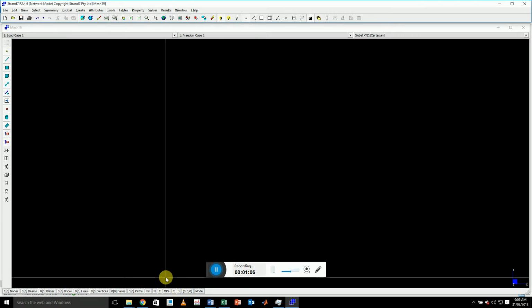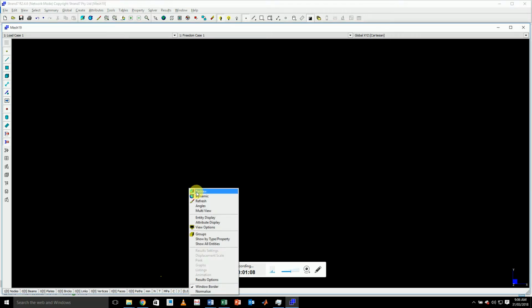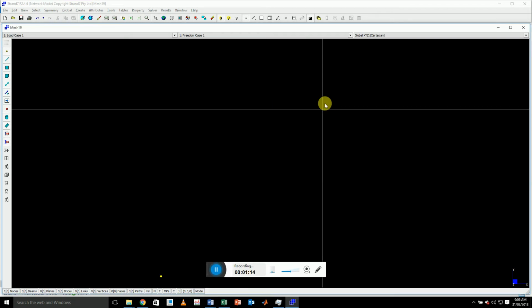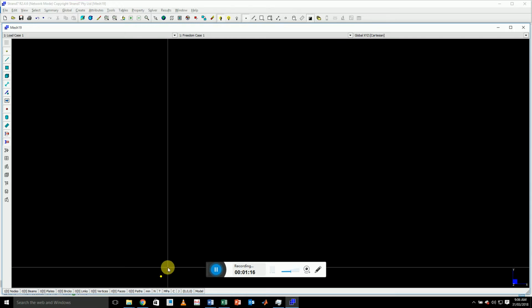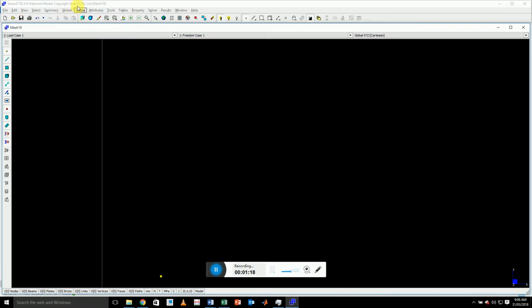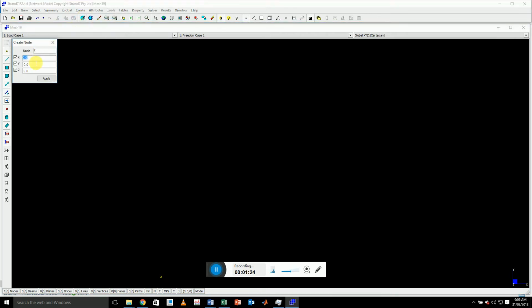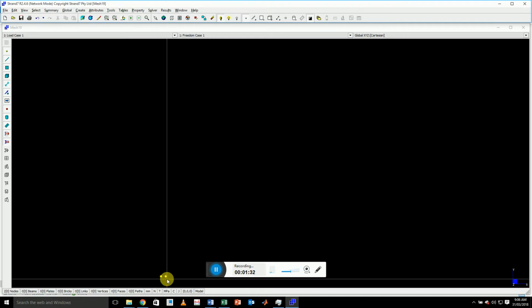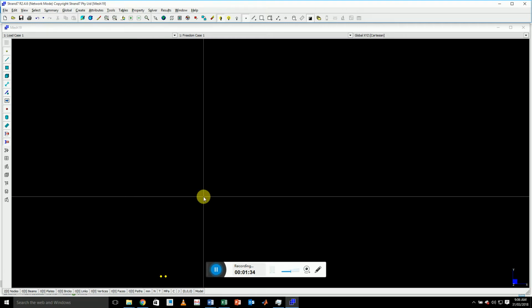Okay. I'm going to make my nodes a little bit bigger so they're easier for you to see, just in case this video isn't coming through at the best resolution. There we go. So that's my first node. We remember that our geometry is going to be made up of nodes connected by beams. So I'm going to make a second node 338 millimeters away, so that we can make a beam to join these two things up.